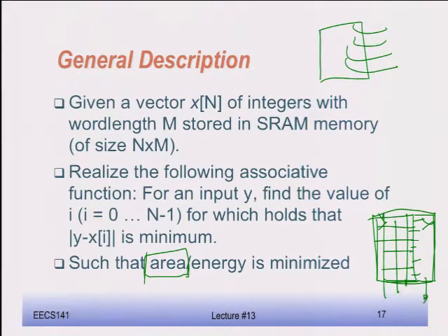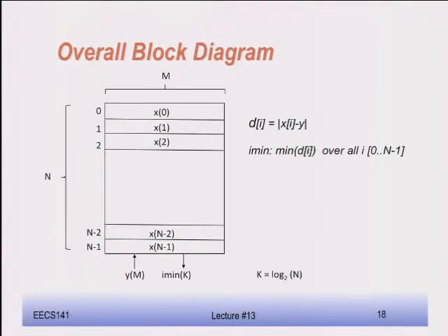Because think about it. Here's what I have. Here's my memory array. So I have n words, each of them storing a value of x. In our project, it's going to be 1024, 10 bits of address. This is going to be 16-bit bytes. So the data word is 16. So a 16 times 1024 memory array. That's really what we're looking at.